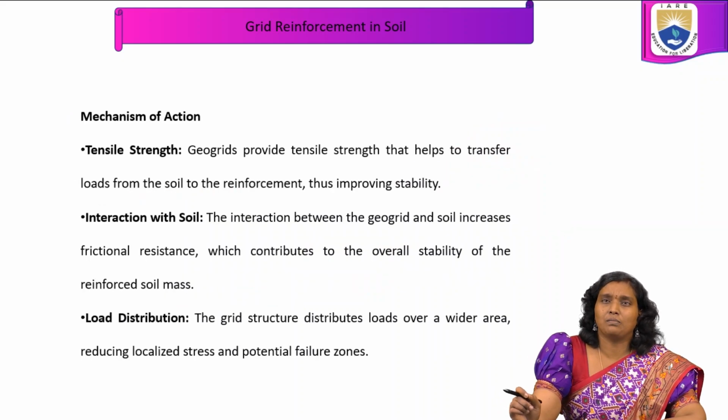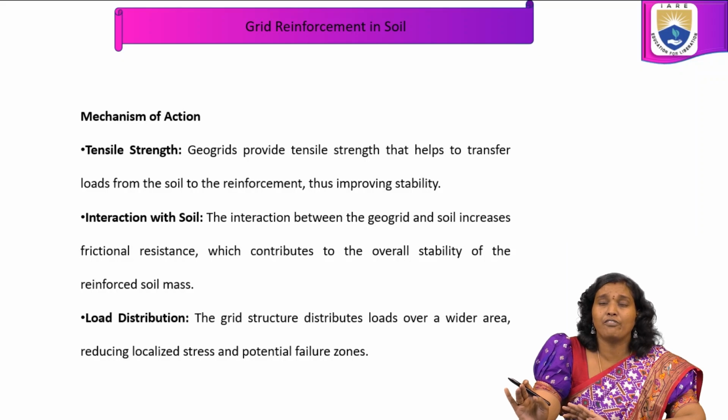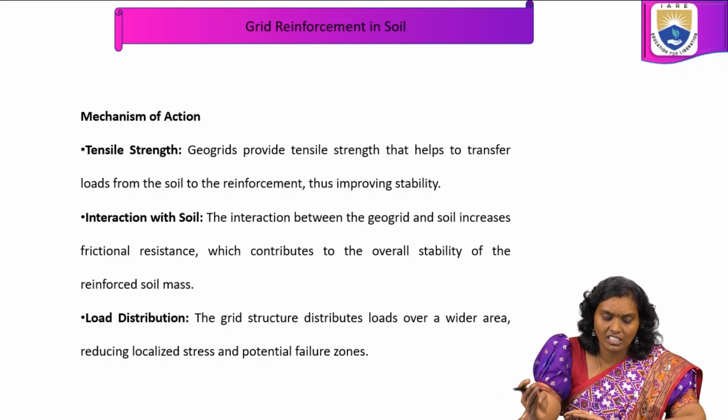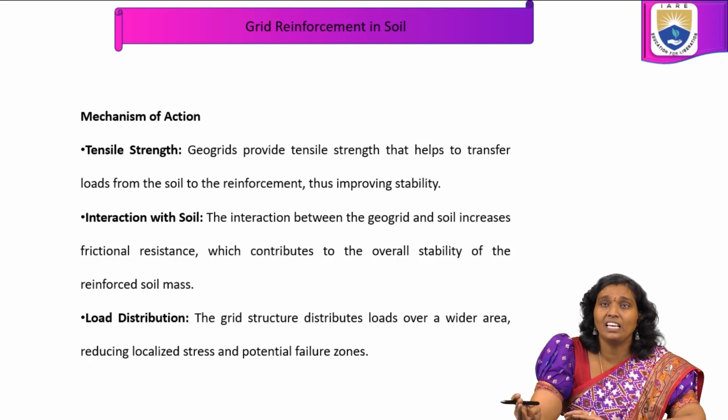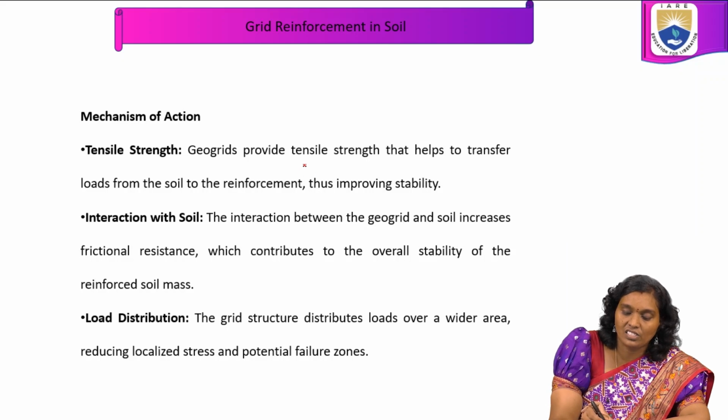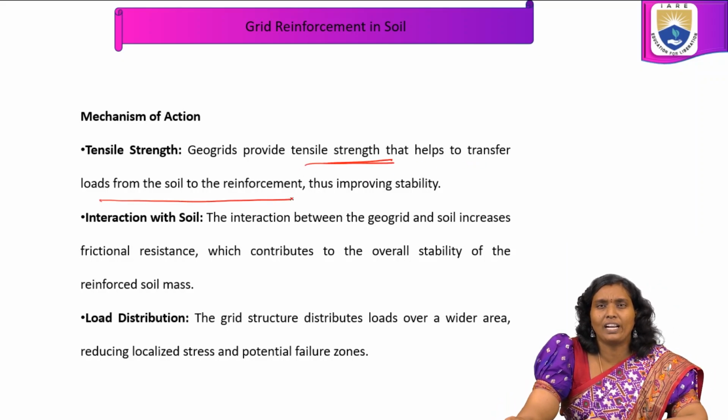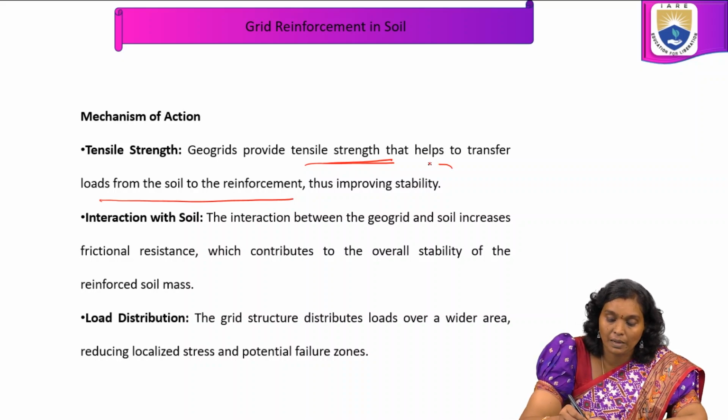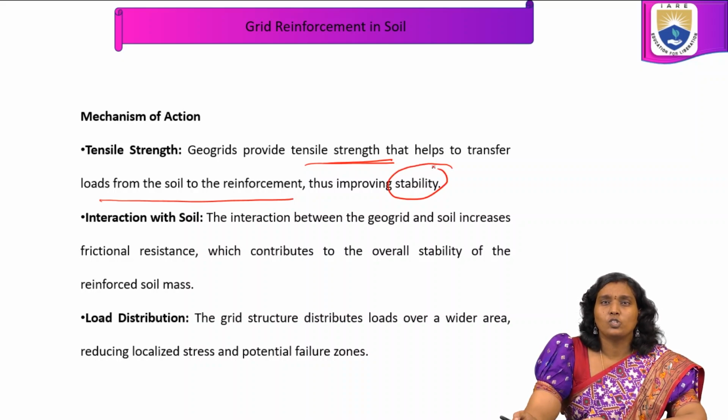Coming to the mechanism of action of grid reinforcement in soil, tensile strength, interaction with soil, and load distribution are the parameters for understanding grid reinforcement. Geogrids provide tensile strength to help transfer loads from the soil to the reinforcement, which improves stability.